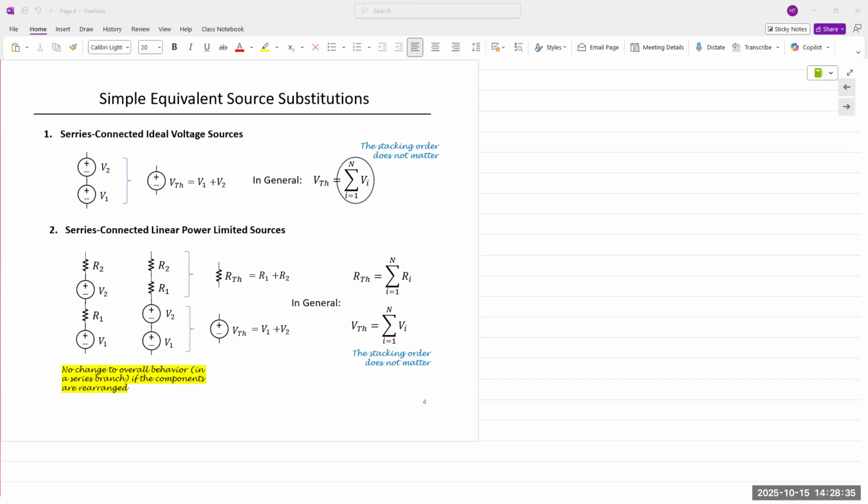But other than that, nothing else to be done to the circuit. And then Req, still measured between the same terminals. You remove the voltage supply, place a short circuit wire in there, measure Req, done. That's your Thevenin resistance. So actual measurements can be done in less than 2 minutes. The theoretical calculations and understanding what it is, that's what you're going to talk about.